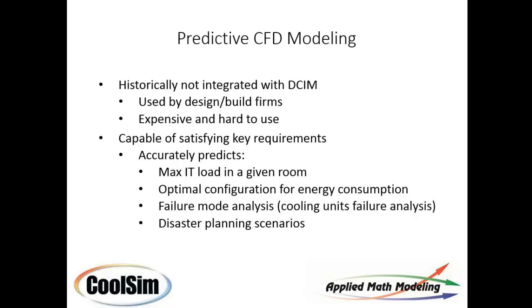Remember that for every kilowatt you put into the room for IT load, it's not uncommon that you actually consume another kilowatt in the cooling system to get that first kilowatt out. So I've given you there a ratio of 1 to 1. It shouldn't be that. It should be that it only takes about 0.25 kilowatts to get a single kilowatt of heat out of the room.